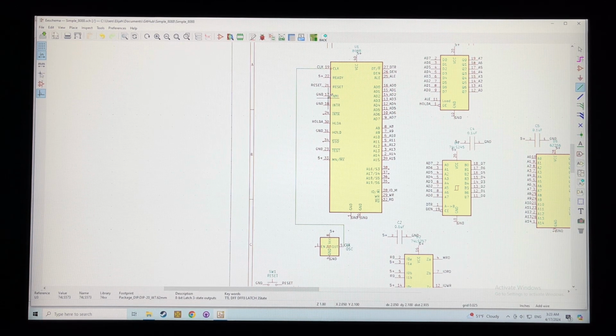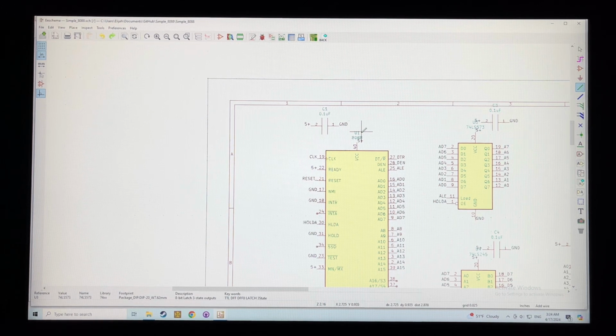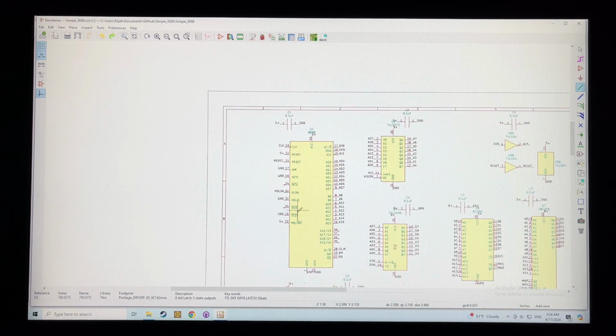I know some guys like to see a visual reference of what connects to what, but that's actually what I do on the circuit board. You can highlight the route on the circuit board and see everything connected. So to me, you can draw it here and then draw it in the PCB, or just do it once. So I'm just going to undo that wire. I go through and label everything. And once you really learn the components that you're working with, it's not too hard to understand how everything ties together without seeing the wires.